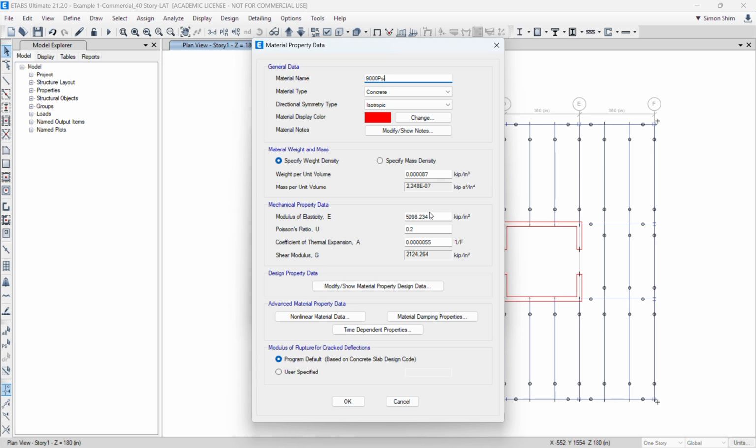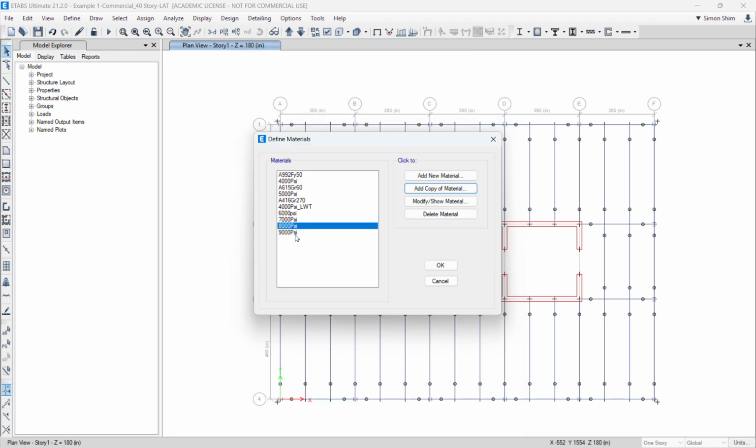So how many concrete strengths do I typically use? It depends, but I think not that many. This is 9 divided by 8. Probably I'm gonna stay with 3 discrete concrete strengths for the wall and column. So I'm gonna use wall concrete strengths of 9, 8, 7, or 9, 7, 5, something like that. It's more engineering judgment. All right.